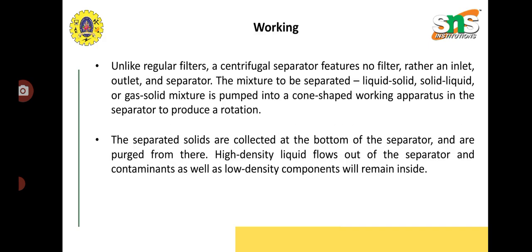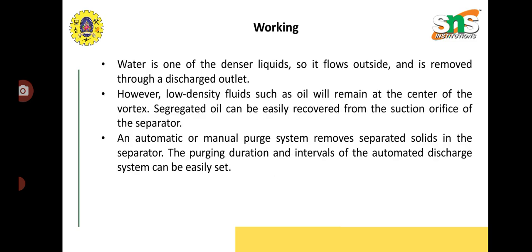And it contains no filter when compared to the other filters. It consists of the inlet, outlet and the separator. The separated solids are collected at the bottom of the separator, and can be removed from the downward section. Water is one of the denser liquids, so it flows outside and is removed through the discharge outlet. Low density fluids such as oil will remain at the center of the vortex, and the segregated oil can be easily recovered from the suction orifice of the separator.